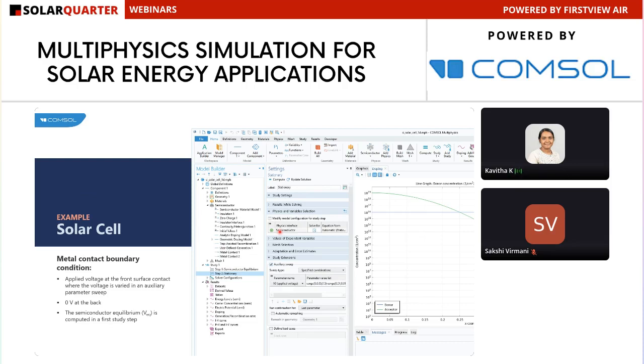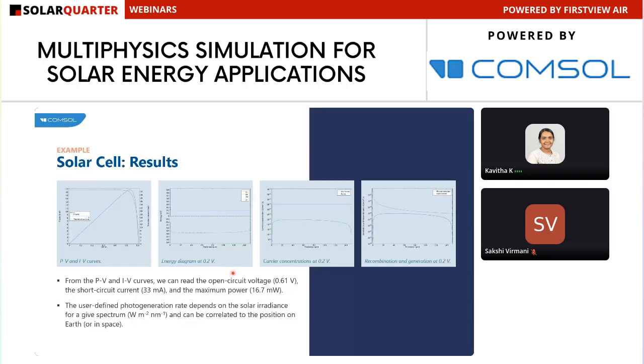And after completion of defining the physics and boundary conditions, you mesh the geometry using the mesh node and perform the stationary study for different biasing voltages. And then you visualize the results. Here in this example, you can see the maximum power generated is almost 16.7 milliwatt. You can also plot the energy diagram, carrier concentration, recombination, and generation rate. So this is about modeling of a solar cell at the semiconductor level.